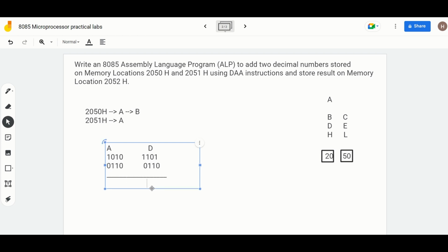the sum will be, you always start the sum from the immediate right part. So 1, then 1 plus 0 again 1, then 1 plus 1 is 10, there will be a carry, so 1 plus 1 again 10. Now that carry is being forwarded to here. 0 plus 0 is 0, but because of the carry which is being forwarded, you will get 1. Then you have 1 plus 1 again 10, so you will get 0 and the carry will be forwarded again.